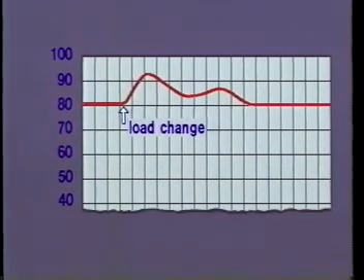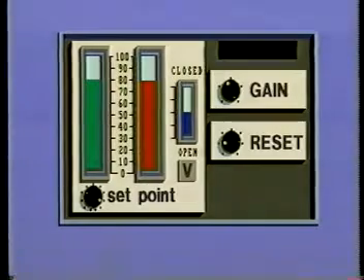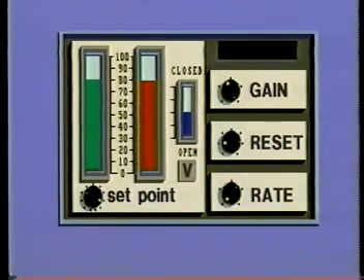It became obvious that the controller did not move the valve fast enough to prevent overpeaking during load changes. If the controller could detect the rate of temperature change and could cause additional valve movement whenever the temperature changed rapidly, overpeaking could be greatly reduced. What was needed was a device that could anticipate overpeaking based on a rapidly increasing or decreasing error signal. Such a device is called a derivative unit, or because it is based on the rate of change of the error signal, it is often called a rate action unit.